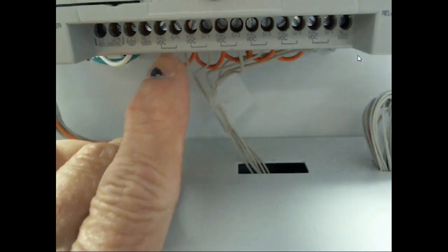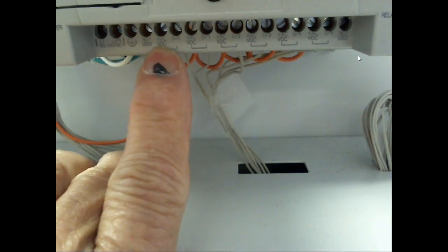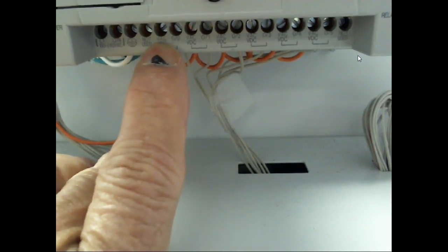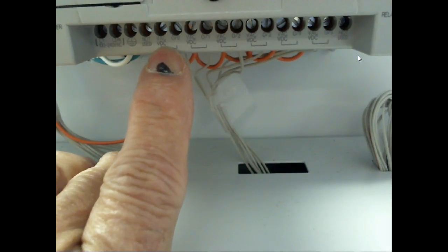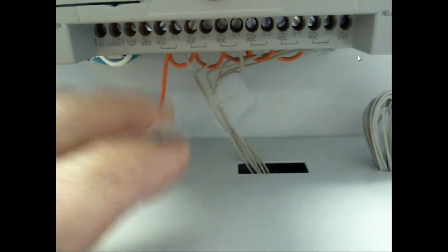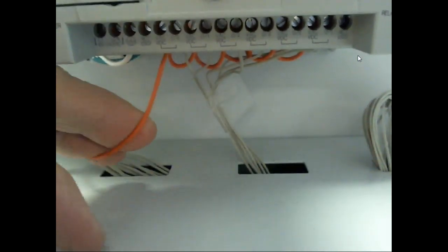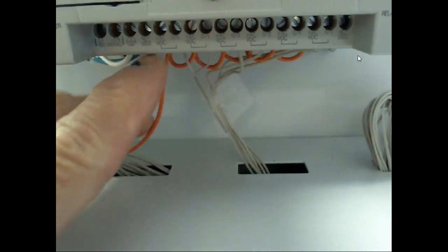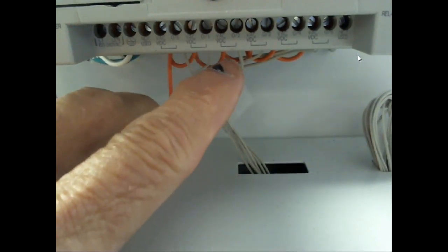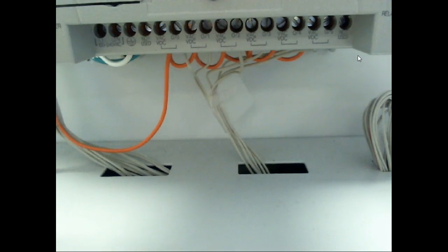So notice I can use two commons here. You'll see what that says? Anybody? Both AC, or I can make it what? Both DC. This is the plus coming in. And notice what I've done to all the commons. I just jumped them together, right? And then these wires on the bottom are actually what's going out to these outputs down at the bottom. Okay? Are we okay so far?